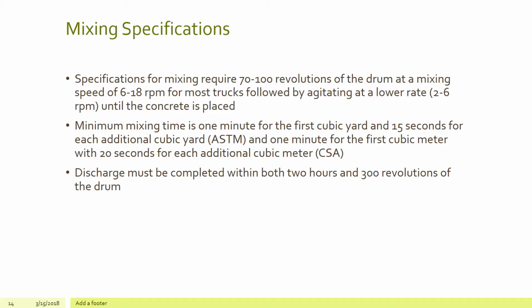And this discharge, again, is what I was saying. If we don't get that done, we get what's called a hot load, and it starts to solidify within the drum, and now we have concerns about it hardening. And of course, as I mentioned, now we're looking to jackhammer all that concrete out of there.